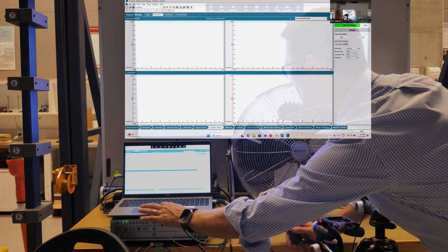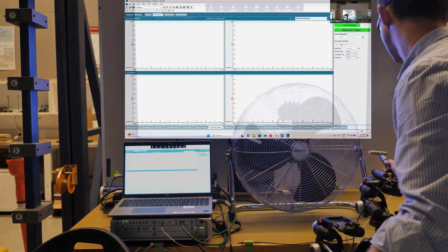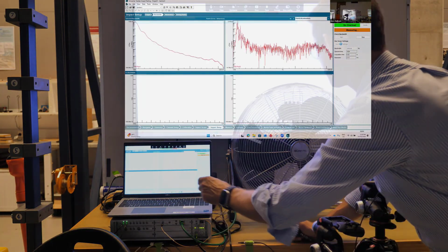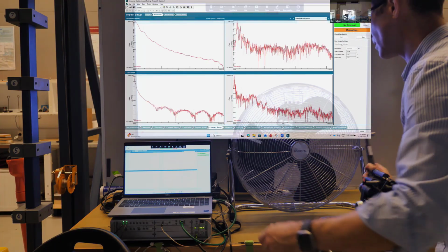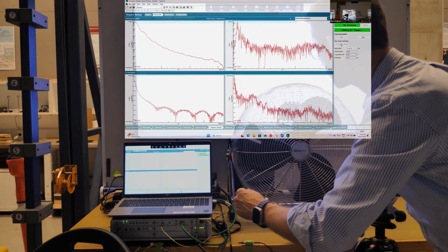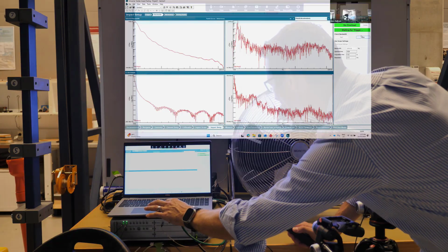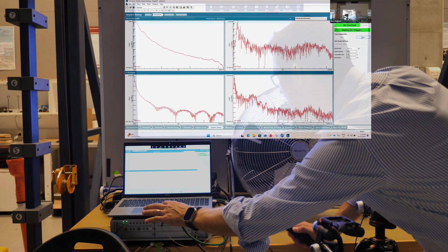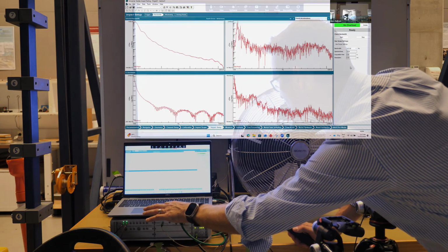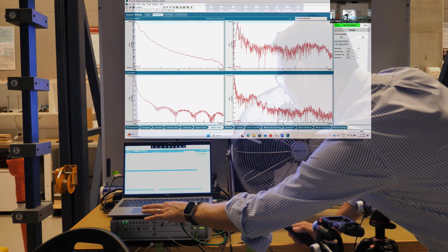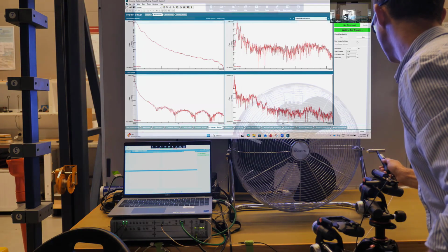In the windowing workbook, or sorry, the bandwidth workbook, I can do some impacts now, and it's not a brilliant impact, and it's not a great structure to do measurements from because obviously it's an assembly, there's lots of loose connections and various things, but I'm getting some energy into the structure. Actually I'm using a bandwidth that's too high. I should have used a bandwidth that was the same as that which I set up in the oscilloscope, which was 512 Hertz. If I'd chosen to use the scope settings, that would have been more sensible. Let's do that again.